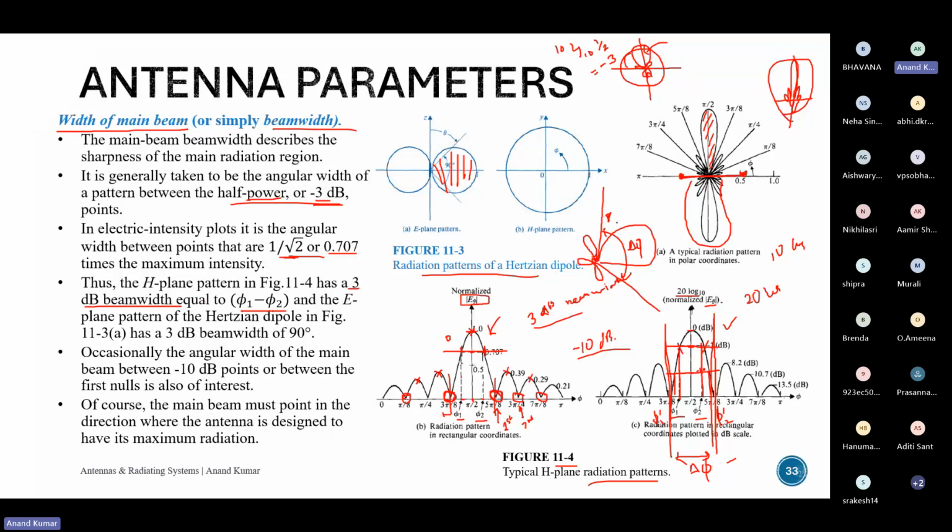But even if your device is inside the beam, because this is the angle you have defined, it may be in a direction where the power is very low. So this device will be receiving very little power, because although it is inside the first null beam width, it is in a position where the power is very low. It would have received more power in one of the minor lobes. So we came up with the 3 dB beam width.